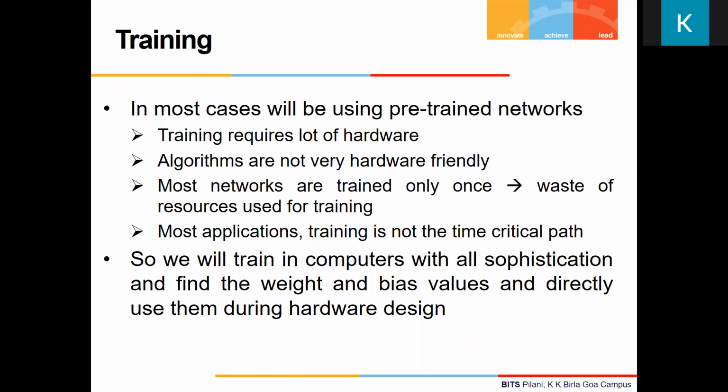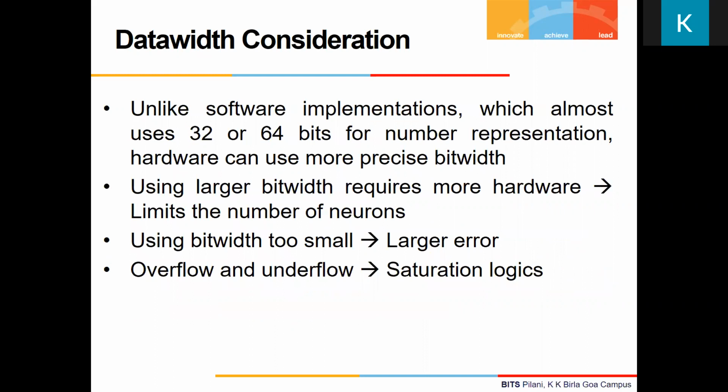So that is what I am going to do. I am not going to do training in hardware. I will do a pre-train. In most cases, personally, I do it using TensorFlow. I extract the weights and biases from that software model, and I directly use those parameters for my hardware implementation.